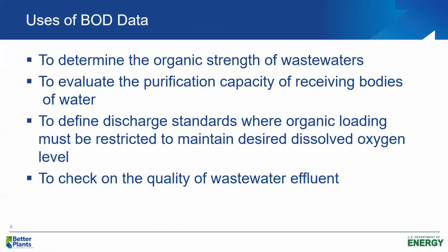BOD data is used in a lot of ways. Again, arguably, I said it's the most important parameter we can run on a wastewater to assess its strength. But typically in medium strength municipal wastewater, I normally use a value of about 200 milligrams per liter as an estimate for the BOD5 concentration.